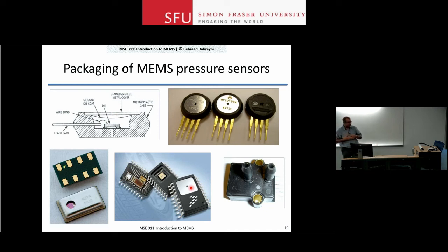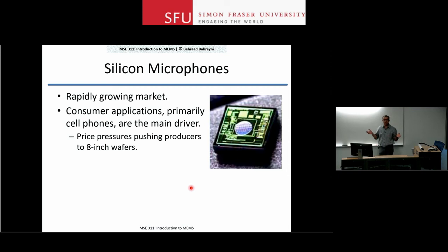A microphone is doing the same job. So what we're doing with a microphone is that when we have sound in an environment, there is an acoustic pressure. This acoustic pressure comes and hits the, for membrane-based microphones, will hit the membrane, and the membrane will start to move back and forth. If we detect those movements, we can estimate the acoustic pressure intensity, right? So when you talk about microphones, structurally they are in most cases the same. You have a membrane that is deflecting in response to an acoustic pressure, and you measure that deflection, right?